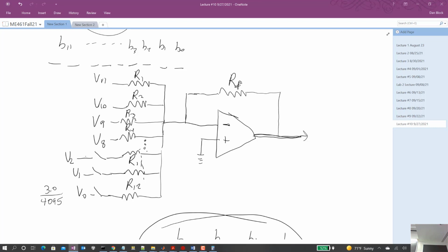Okay. And now the key, the hard part, this is an op-amp. Technically, we could just patch this up with an op-amp on a breadboard. Okay? Now it takes some doing. All these resistances right here have to be really precise, because what's happening here is it's the same voltage coming into each of these ports, but the gain from R4 and the feedback resistor creates a gain less than 1 that multiplies by 3 volts to get us that fraction of the voltage.